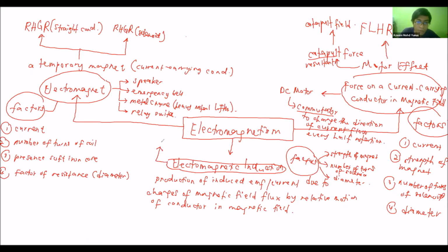We introduce Fleming's right hand rule to determine the direction of induced current. How are we going to use Fleming's right hand rule? First, align the magnetic field towards the south, and then the force either upwards or downwards or forward or backwards. And then lastly, we can know the direction of the induced current, either into or out of the page.